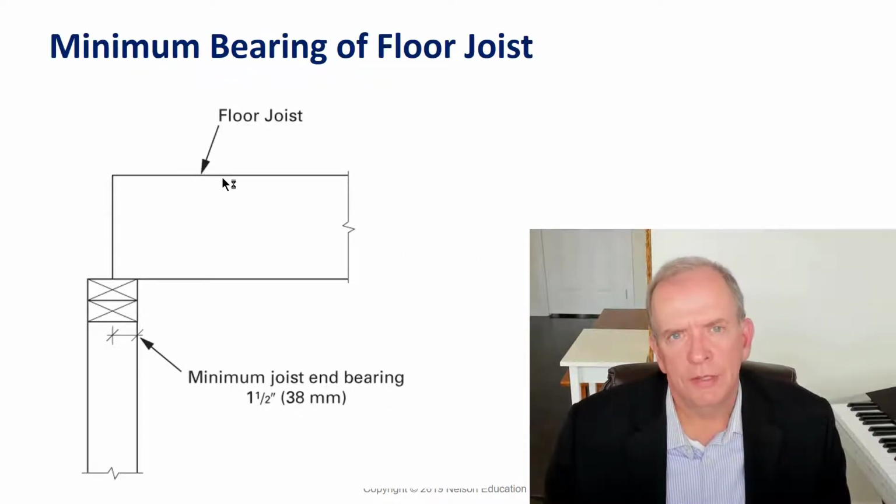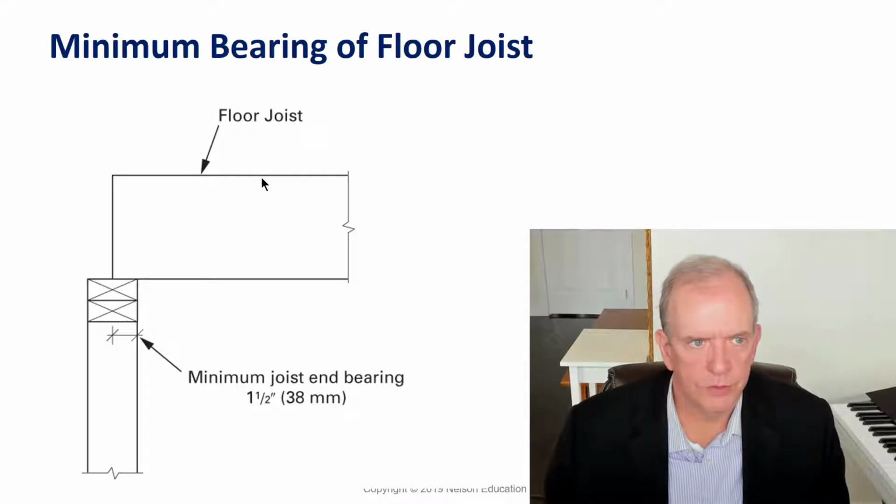Usually we use 5/8 tongue and groove for subfloors. That's the most common, or 3/4 inch tongue and groove for subfloors. So that's when we're using 16 inches or 12 inches.